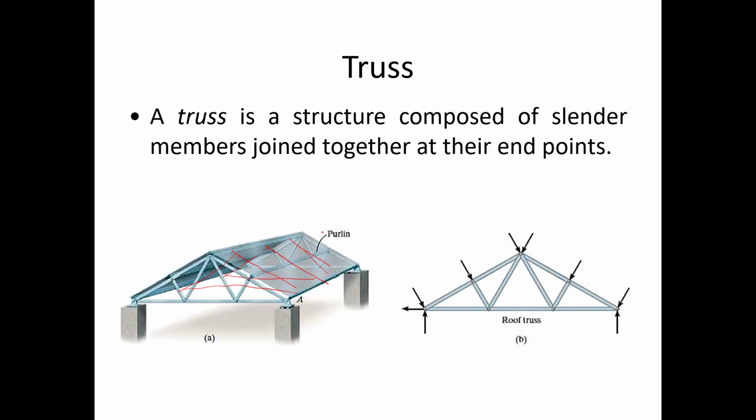If you're going to make this complex, in the aspect of civil engineering or structural engineering, once the roof is installed, aside from determining the load coming from the dead load or the roof load, of course we analyze it as well using the standards of the wind load and also the standards coming from the code, which is the earthquake load. So there is a lot more analysis compared to the basic ones, which is just the live load and the dead load.